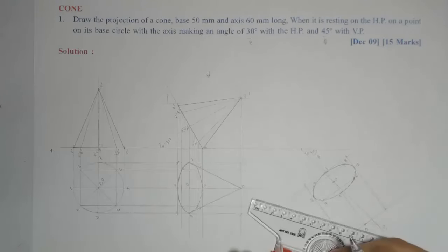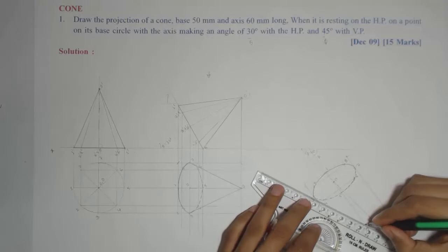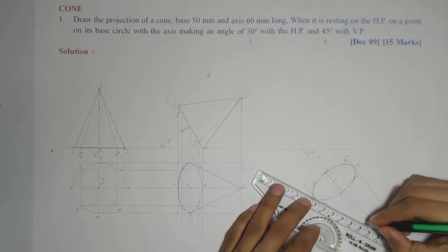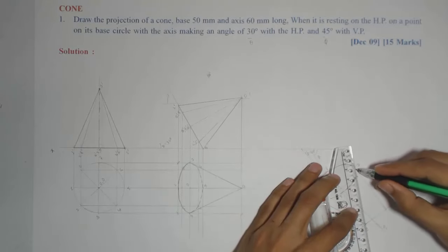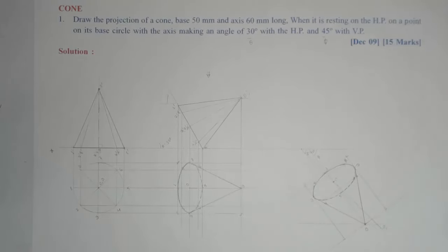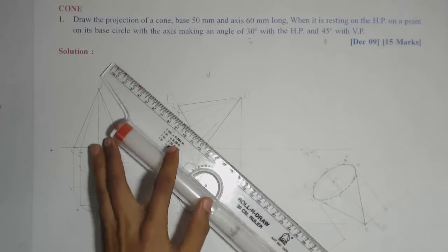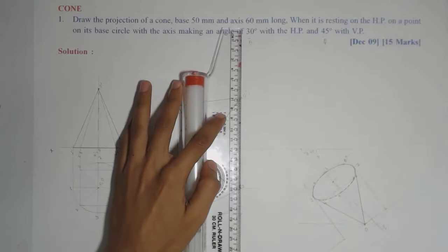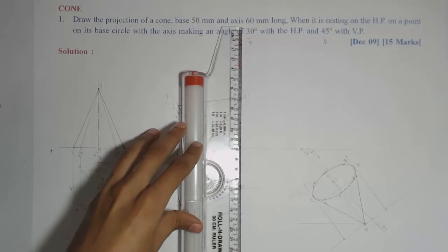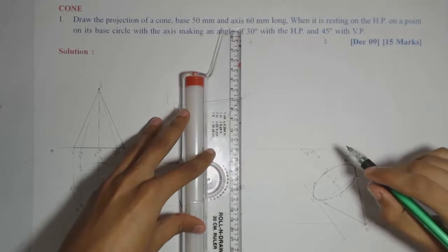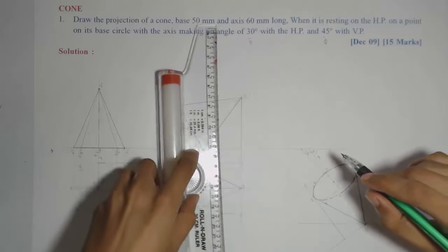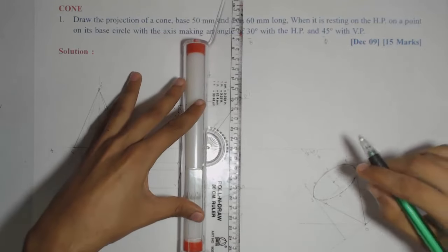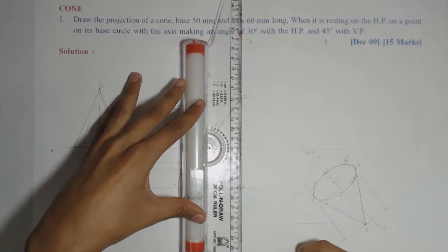Okay. Now we'll draw the tangents. Not exactly meeting at 3 but before 3, and here the tangent not meeting exactly at 7 but before 7. Okay. Now after redrawing this stage, we'll complete the final view by usual method, dropping the projectors from each corner and corresponding projector from front view. Be careful while using the roller scale.